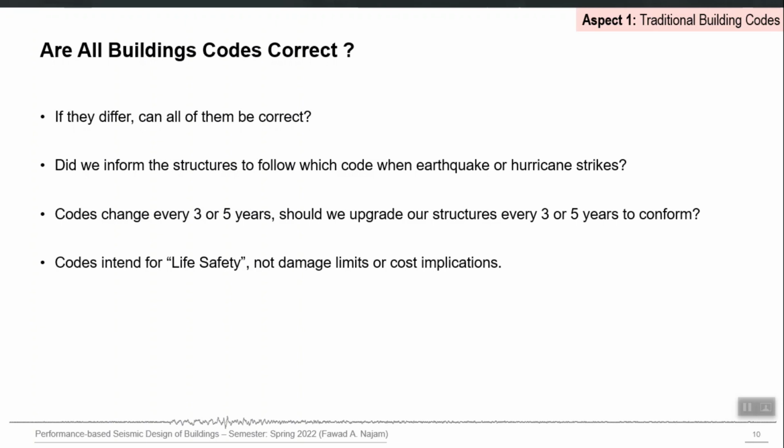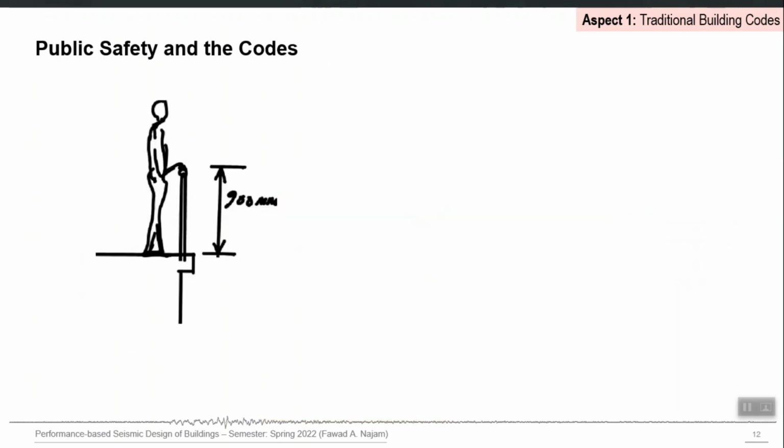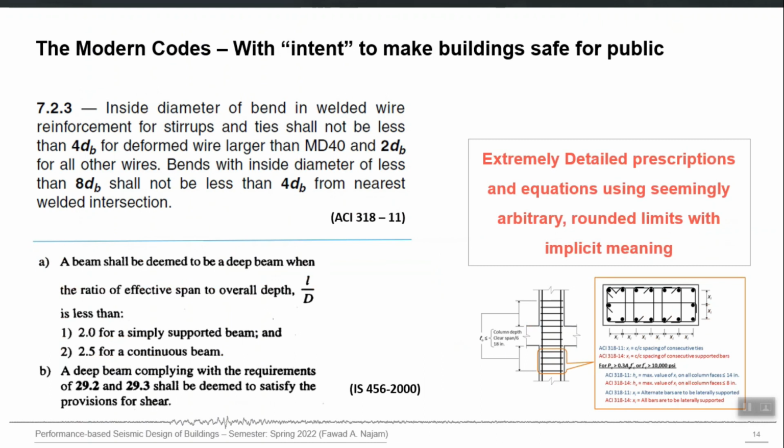And in several countries actually, that system or framework of PBD actually exists at the building control or building authority level, right. So the second aspect was about the rapid urbanization. I actually gave you a few examples also of how a prescriptive or traditional building code is different from a performance oriented building code, because in the performance oriented approach we directly mention the performance, we directly mention what is required, right. We don't give a cookbook type procedure to implicitly reach that performance. We directly mention that this is the performance and you have to show explicitly that this performance is met.